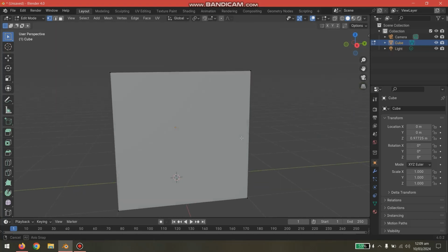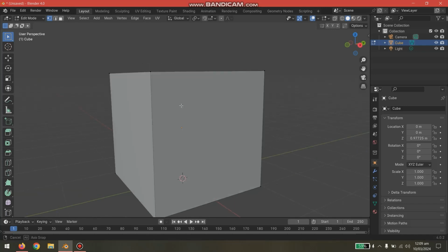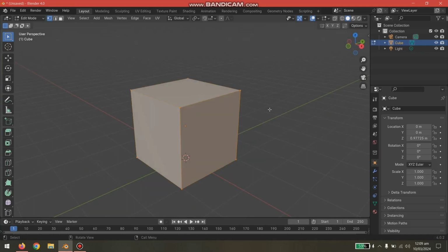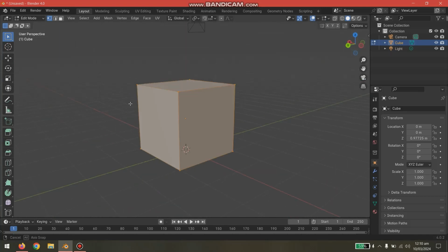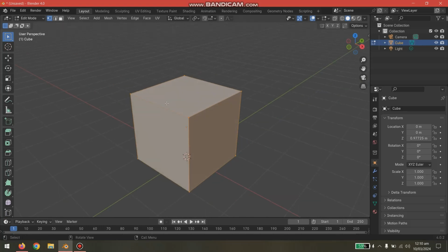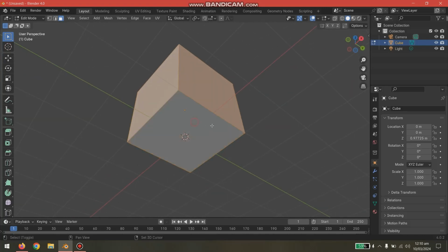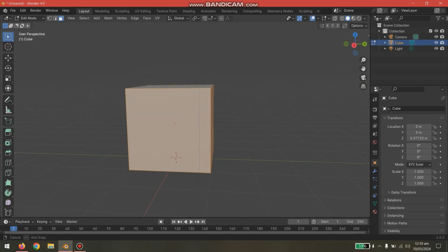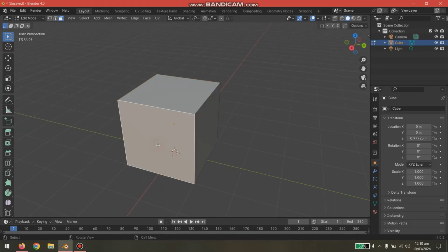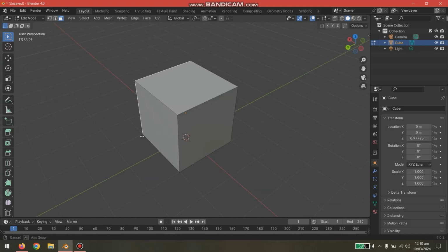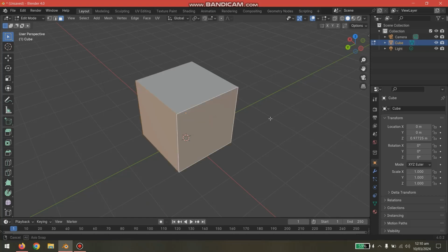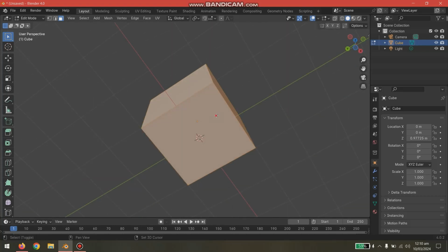If you want this face to have multiple areas to be modified separately, just select this by going to edit mode, pressing A for all. So you can see here I have selected all sides. If I'm creating a building, I do not need these. So go to the first selection, uncheck these by holding shift and clicking. So it will uncheck those and keep the other ones. If I click directly, you can see all selections are removed. So it's better to use the shift key or A press and just exclude those spaces that you don't want.